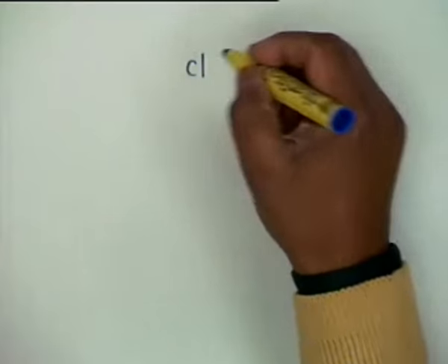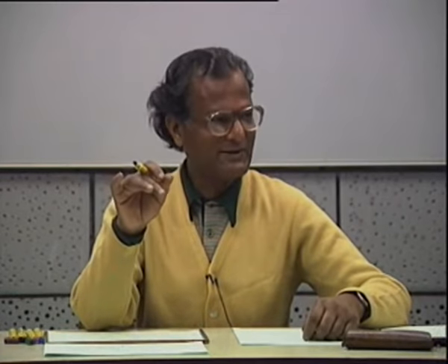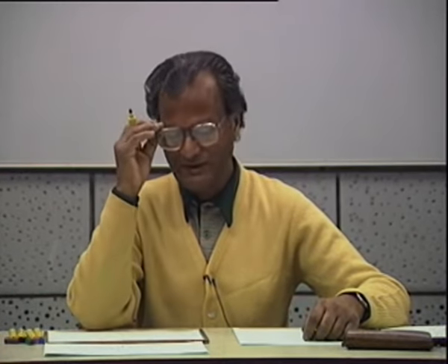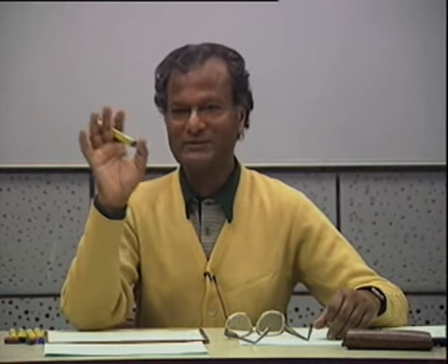The next point that we take up, we have considered class AB. We will come back to class B and class AB when we calculate efficiency. Okay, that means how much power is delivered to the load as compared to the power dissipated in the transistor. We would like zero power to be dissipated in the transistor. But you see, even in class B, the quiescent dissipation is zero. That is, when there is no signal, there is no dissipation. Actual class B, suppose there is no crossover distortion, okay? It is not class AB, so at the quiescent point there is no dissipation.